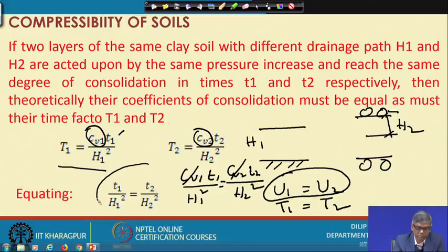So, for a particular soil, when a laboratory test is conducted on a particular thickness, and if it is asked to find the actual time required for the field thickness, one can directly use this relationship to find the timing. So, this is another important piece of information which can be used in solving problems.